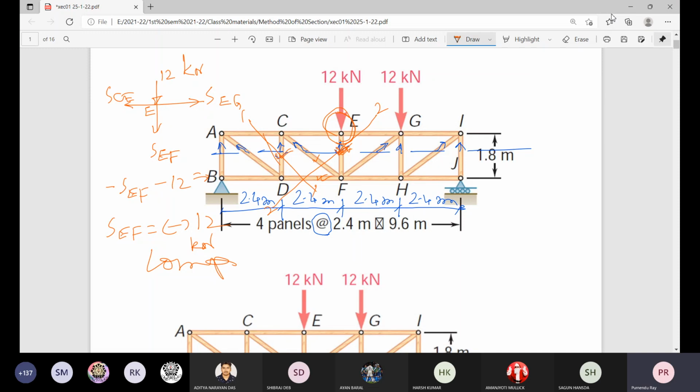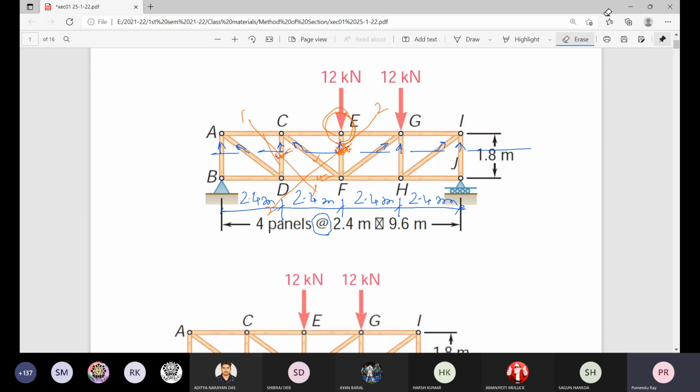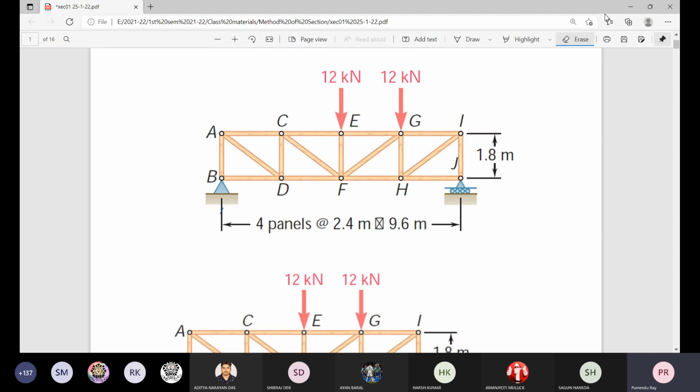Okay. So there is no such hard and fast guideline on how you need to solve it. Any method. In fact, in a perfectly geometrical way also you can solve it; that is the pure graphical method. For simple joints, where 3 forces are there, one in the form of reaction or applied force and the other 2 unknown member forces, you can draw the vector polygon in the form of a triangle. But in this 45 minute class, it is really difficult to give you all knowledge about this. You have to go through the things individually and independently.